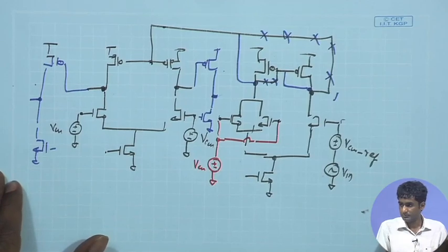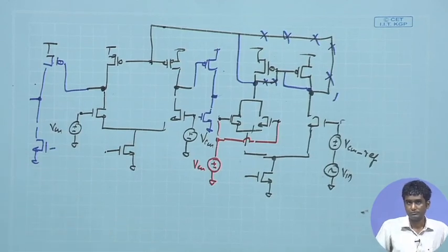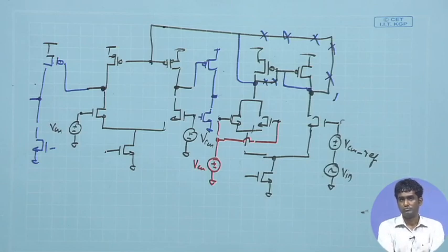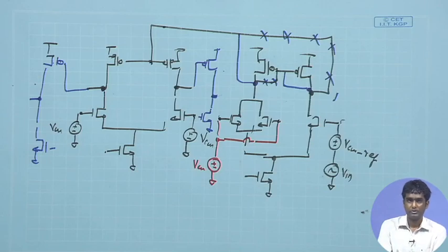So, in the error amplifier, for the first part where we are giving input to the two gates, we want them to be equal to the output of the common source amplifier, right? Yes. So, we want the output of the common source amplifier to be close to VCM ref, right? So, why are we giving VCM? We should give VCM ref, that is the expected value.